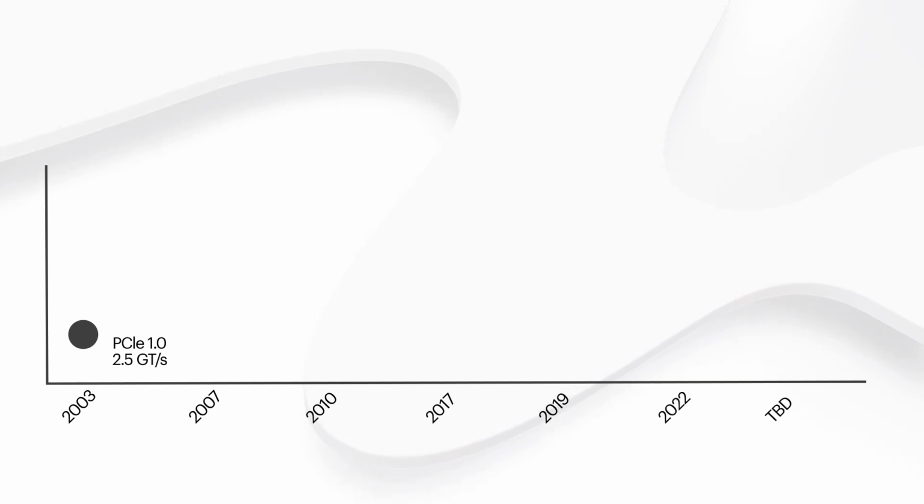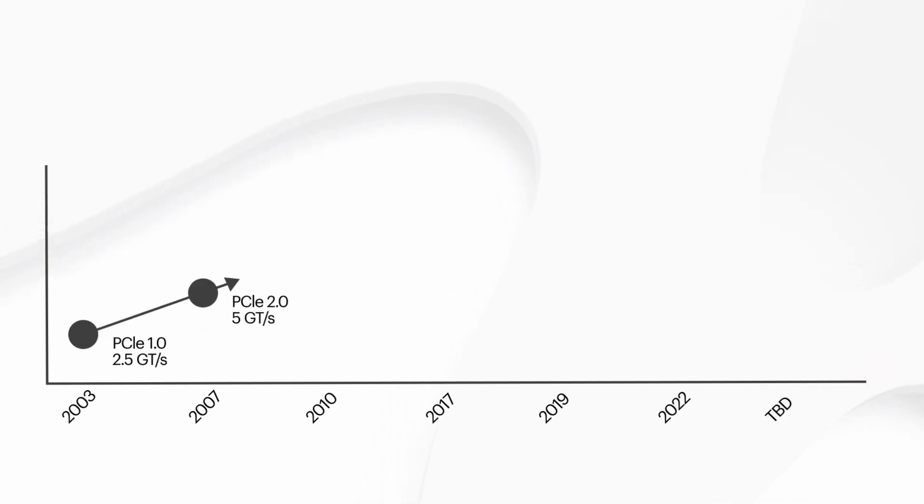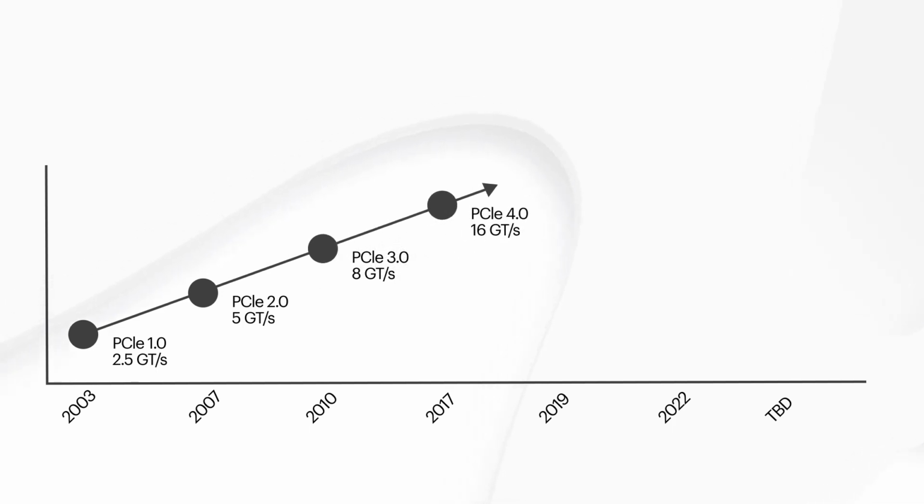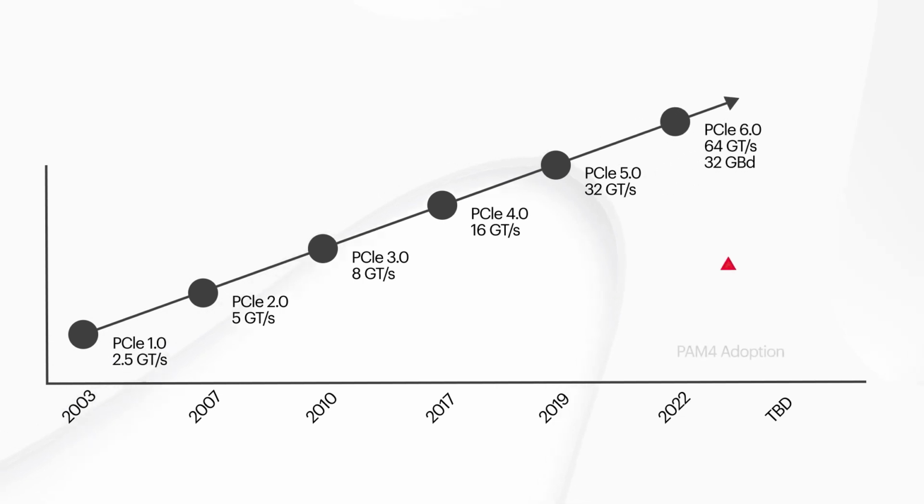Sure. So, if we go back to the very beginning of high-speed serial with PCI Express Gen 1, it was 2.5 gigabit per second NRZ. And that required a 13 gigahertz oscilloscope. So we had lots of bandwidth relative to the baud rate that we were trying to push through a channel. As data rates have gone from 2.5 gigabits per second per lane on PCI Express, that I'm using as an example, all the way to the newest generation, PCI Express Gen 6, is 64 gigabits per second.